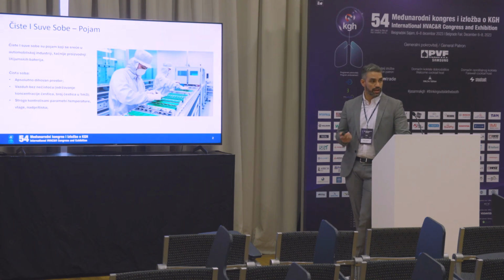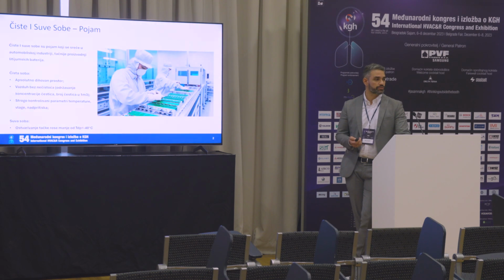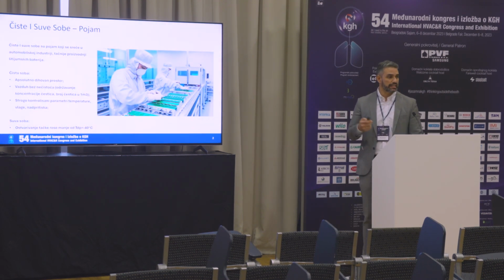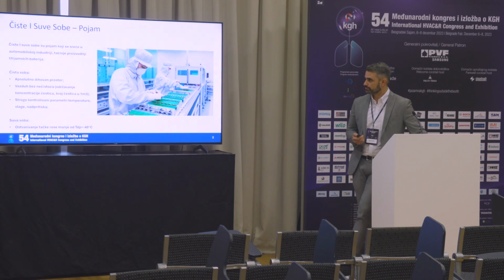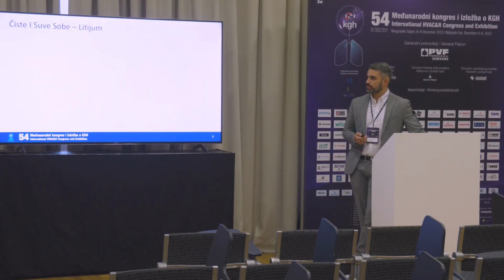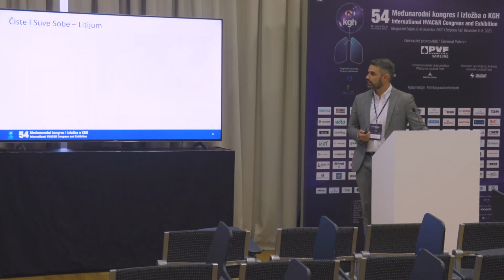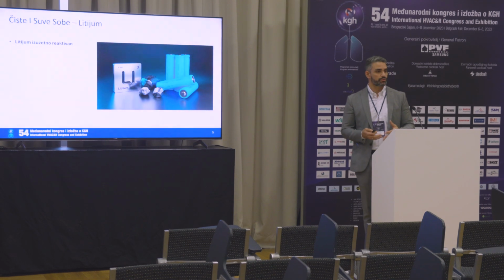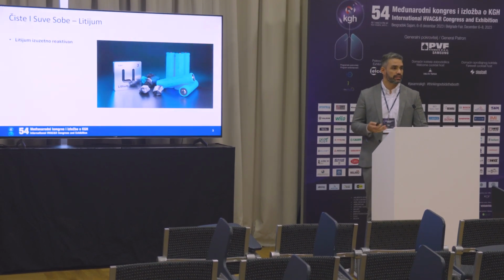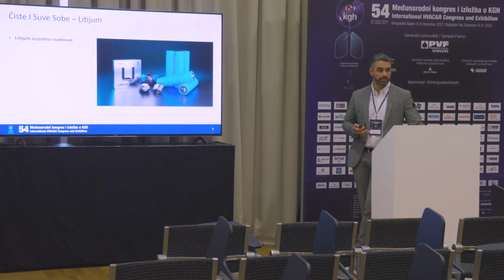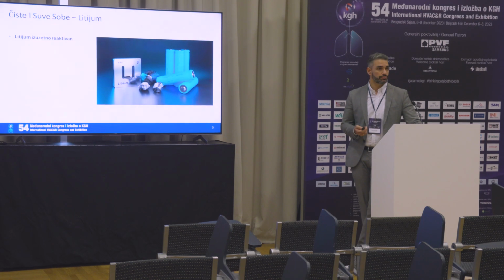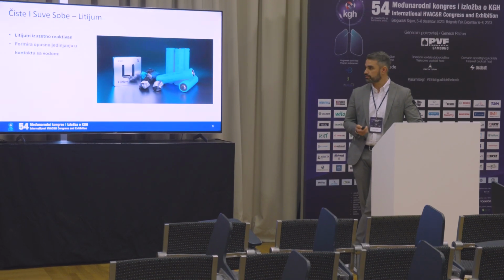In relation to the dry room, we need to keep a low dew point of minus 40. These parameters combined together make a clean and dry room. Why is this important, especially when speaking about lithium? Lithium itself is the basis for production of electric vehicles, that is, the lithium battery, but lithium in its pure form is highly reactive to water.